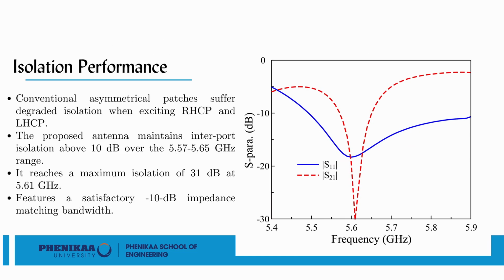A known limitation in the literature is that utilizing a conventional asymmetrical patch for both right and left-hand polarization generally results in significantly degraded isolation between the ports. However, the plotted S parameters for our design validate its stability.